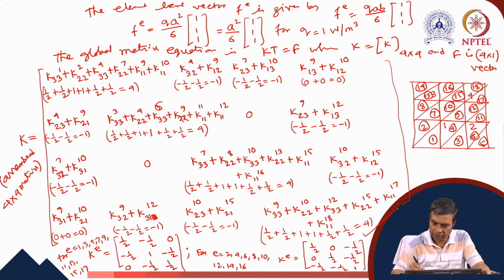So this is the 4 by 4 matrix and the local node numbering for two types of elements. We indicate it once more in this portion. So this is local node 1, local node 2, local node 3 for the odd number of orientation. For the even number elements, we have this orientation as 1, 2, 3. Both of these triangles are right angled triangles.